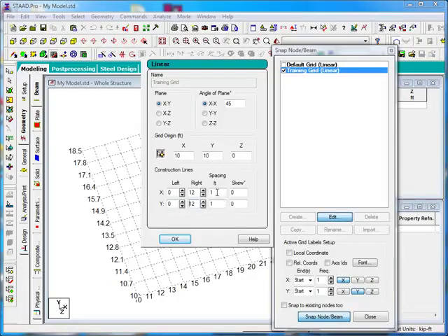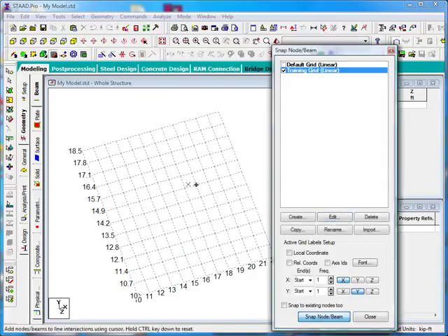I'll leave the spacing values set to 1 foot for each of those different directions, and I'll also leave the skew angle set to 0 degrees so that we have an orthogonal system of grid lines here in our training grid. And with that, what I'll do is click OK. That makes it so that all those changes are saved and closes that little sidecar menu.